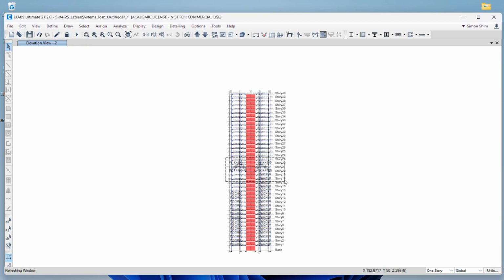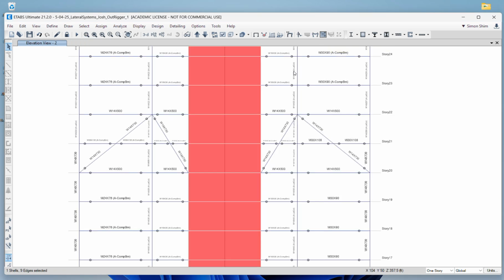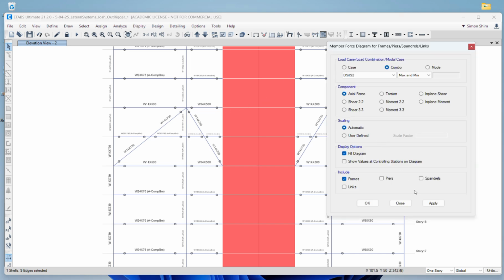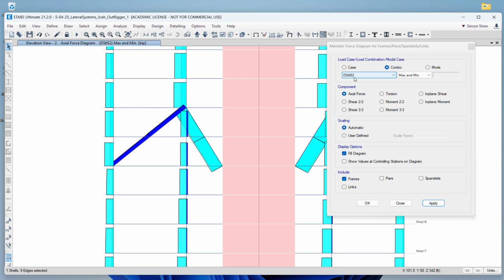Before you design any members, you'd better make sure that your loading makes sense and is realistic. So I think based upon that 1.2, that 1.6 live, you still see that you have this condition.